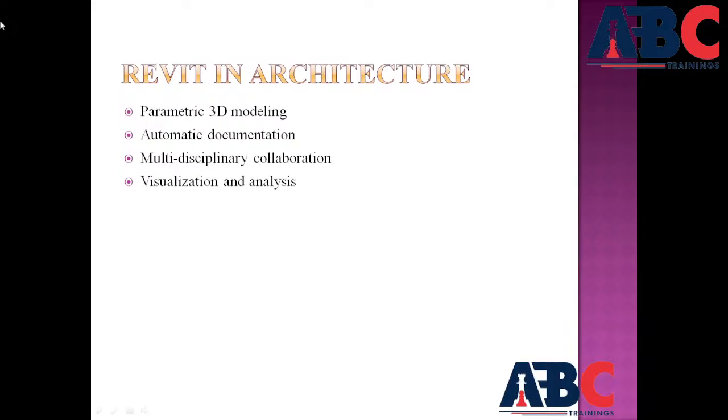If I open a Revit model, I will notice how elements like walls, doors, windows are intelligent objects, not just lines. If you are modifying one view, Revit will automatically update all other associated views, like plan, elevation, schedules. Suppose I'm doing a structure and I have to add one partition wall to a building, and I'm adding it in a floor plan, in a single level. I just put it in a plan, and after that it will automatically get updated in the elevations, in the sections,